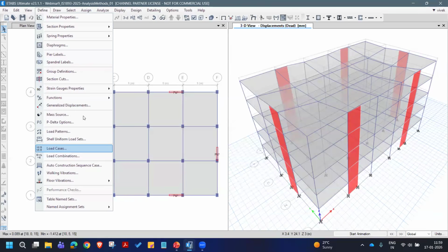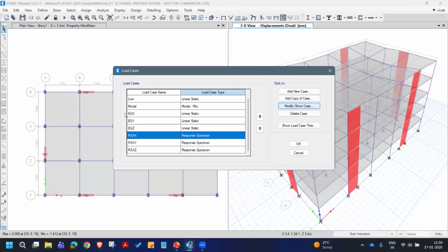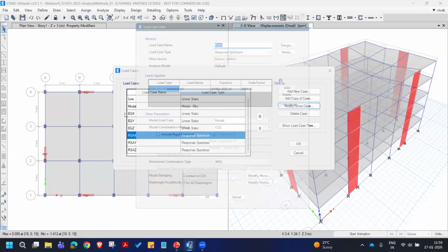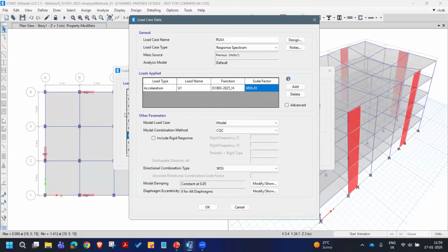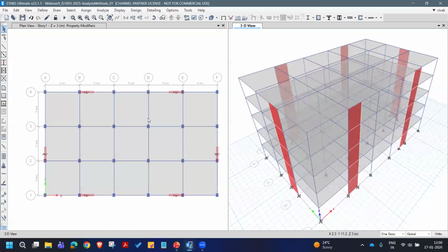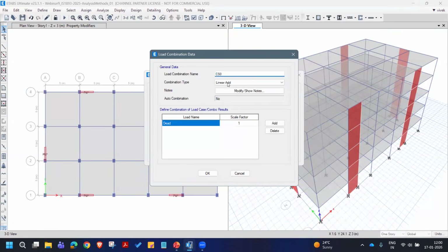So we will have to handle this in a multiple model approach: one model without the omega factor load combinations, and one with the additional combinations, because the omega factor is applicable only for the vertical elements, and shear walls will have another omega factor depending on the aspect ratios. So this needs a proper implementation. At this point of time, we'll have to handle it in one more model that has only these combinations. For now, you can also have the additional combinations in the same model just for demonstrating this.